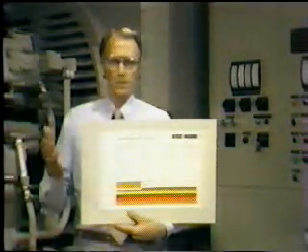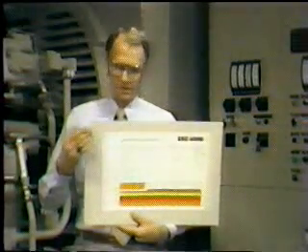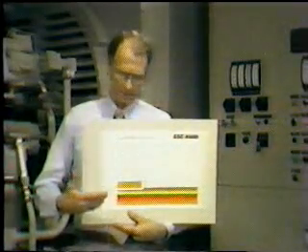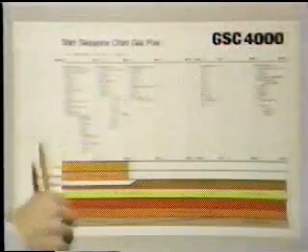Now, another useful tool for troubleshooting is the start sequence. Start sequence illustrates the relationship between time, speed, mechanical events, and electrical events. Across the top of the chart is the engine speed, and down here is elapsed time. The top half of the chart indicates when the electrical events occur in relation to time and speed. The bottom half of the chart indicates the mechanical events in relation to time, speed, and the electrical events.